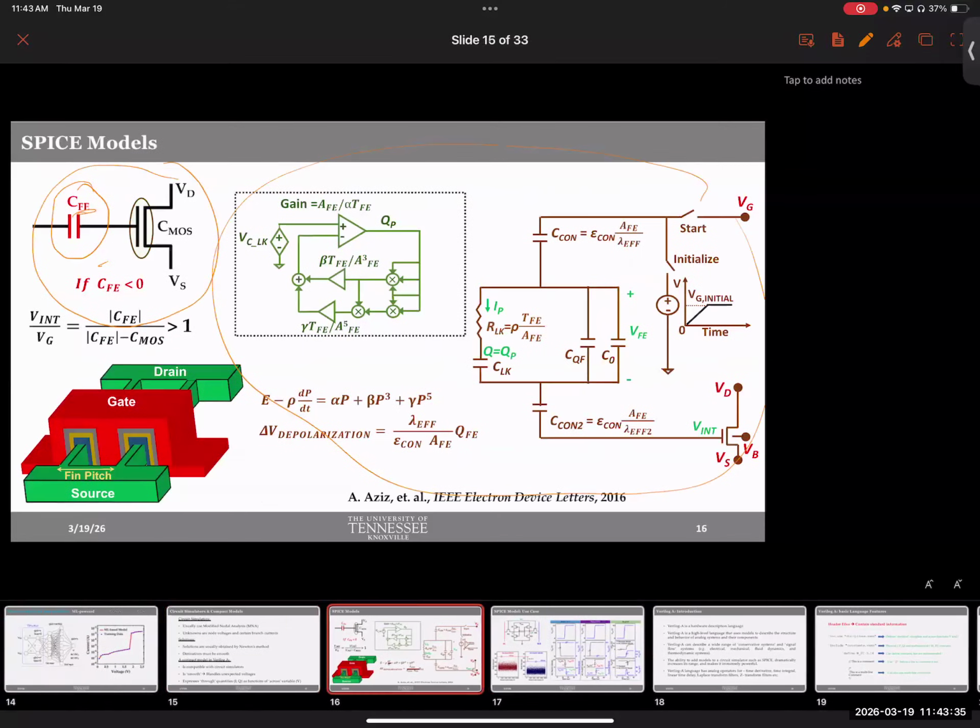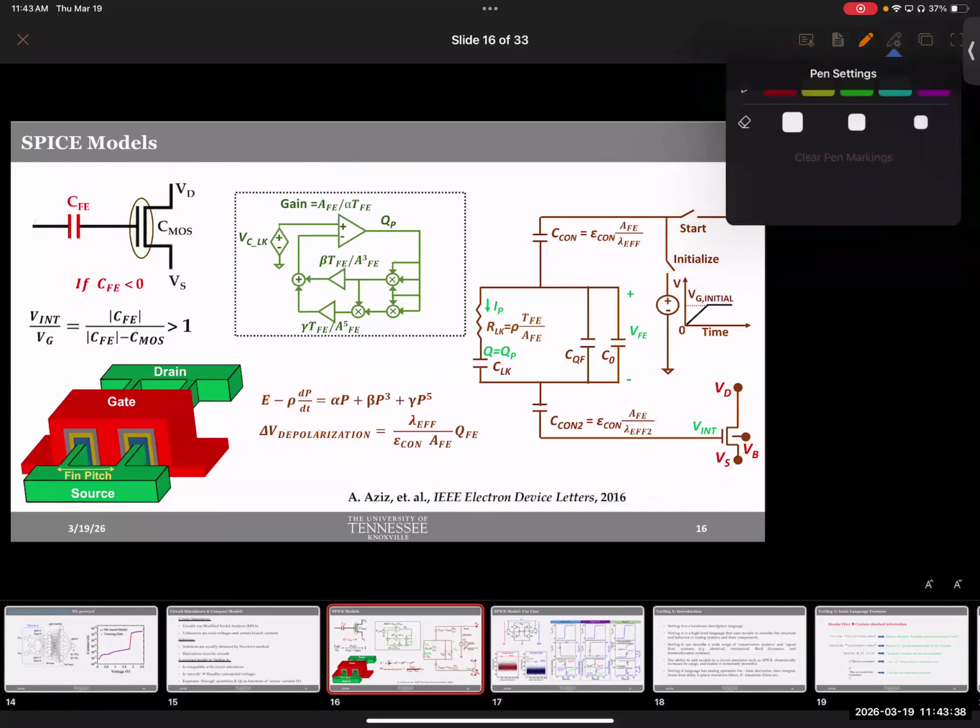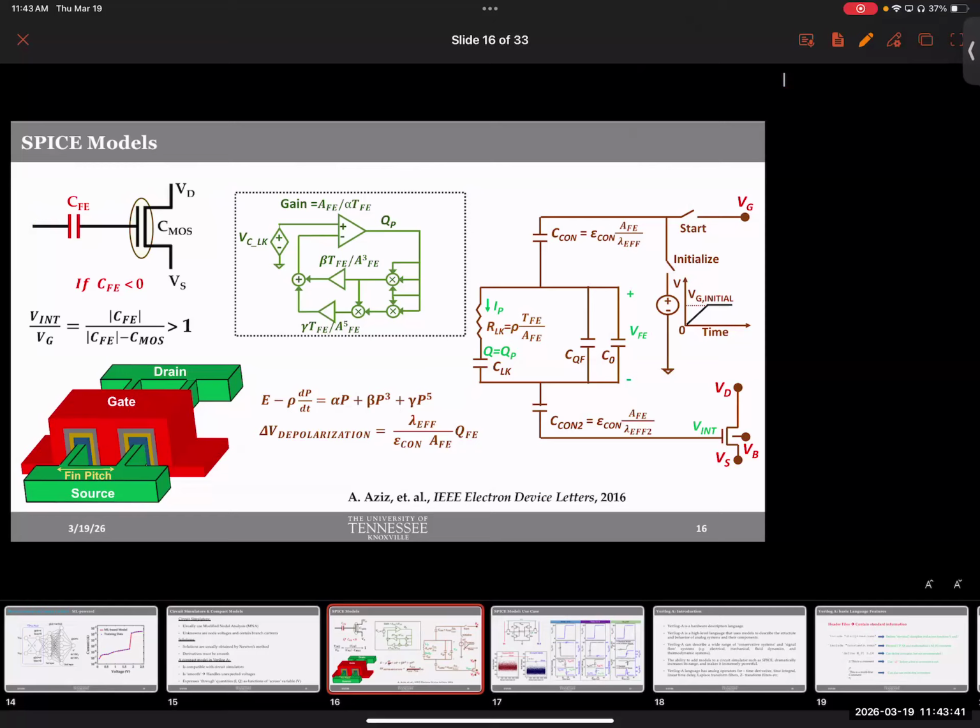Okay, let me show you one thing as to what I mean by that. Notice, this is not in Verilog-A, but in Verilog-A, similar situations could arise. This is in SPICE. So notice, this is an independent block. It is not going anywhere. Is it going anywhere? No, it's basically an independent circuit. Okay, so what it does is it calculates something, and that something, say QP, is then used in a different portion of the circuit. So they're not physically connected. So this is an intermediate stage. It is helping me calculate something, and that is being used somewhere else. Okay? So when you try to solve KCL and KVL, there is no connection between these two circuits.